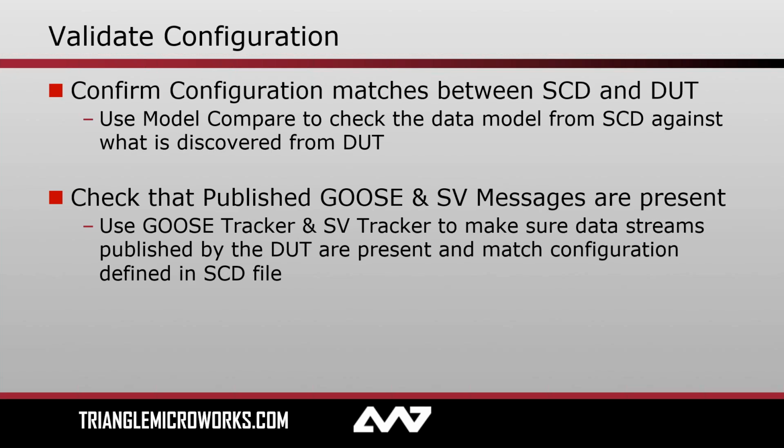Model compare is the name of the feature in Test Suite Pro that allows this, but what it's doing in the background is a discovery. Discovery is a feature within 62850 where a client can reach out to a server and ask for the server to describe itself, describe its own data model, and then model compare is comparing the results of that discovery against what's defined in the SCL file.